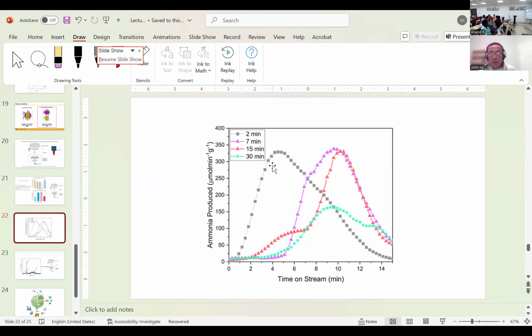Okay, so anyway, this is basically a different angle to look at the pretreatment, shorter time, longer time, but the ammonia coming out is different. With the 2-minute treatment, because the plasma treated the material, the nitride didn't penetrate very deep in the bulk. They're probably in the subsurface. That means when hydrogen comes in, they dissolve. So 7 minutes, same thing. The longer you treat, the more the penetration depth and the more difficult for them to come out.